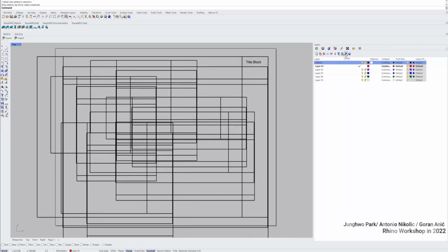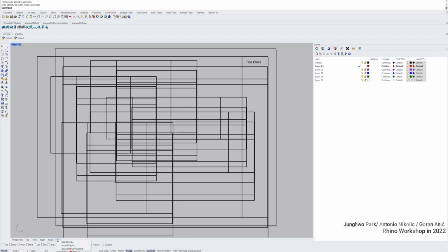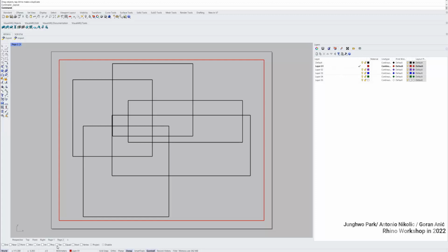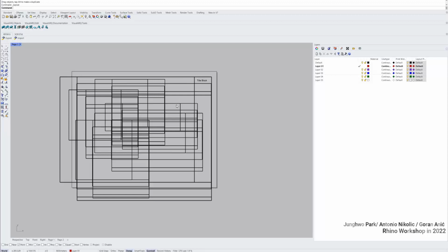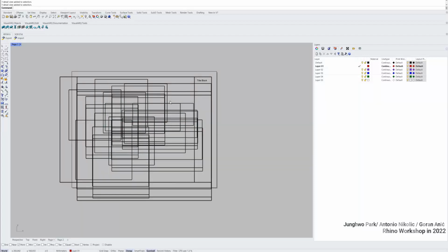I suppose it's a standard option to copy this viewport twice on the layout. You can make a lot of layouts. And you can also organize them like a sheet, not just a layout. Now inside the layout you can copy the viewport. If you double click, then this is the viewport, so you can scale it accordingly. Yeah, like in Revit. AutoCAD. Yeah, like in AutoCAD. Yeah, exactly. Revit.